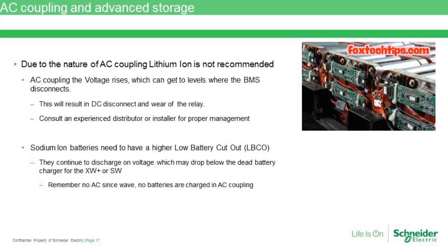Just simply looking at the numbers from manufacturers, typically we can see 3 or 4, maybe 500 cycles out of 100% depth of discharge on a set of batteries. So if they're only losing power a couple times a year for 24 or even 48 hours, that's only 4 cycles a year. So if we multiply that out by the life of the batteries, they're going to literally age out. The chemicals inside are going to not be available to the system because of just the natural aging process within those batteries.